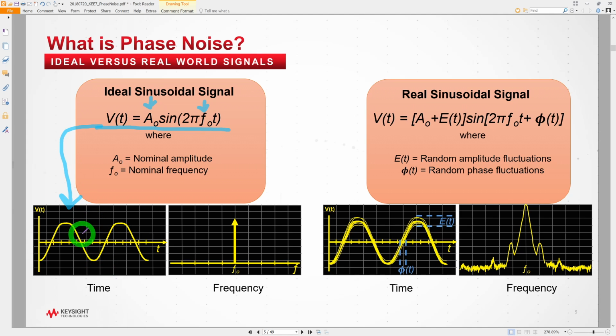Although I have to say this is a pretty bad sinusoid, because the top of it is not round, it's flat, which means that this is going to have harmonics associated with it. And I've made videos about how these harmonics show up and how they have intermodulation products with other sinusoids that are present in the system, and we've talked about that in different videos. But for the purposes of this one, let's assume this is a perfect sinusoid.